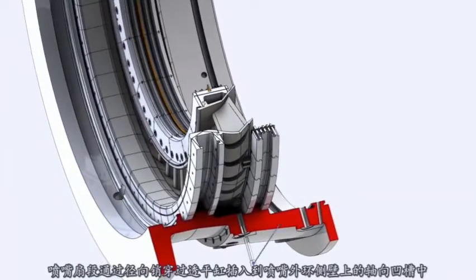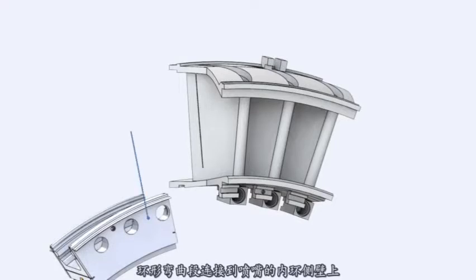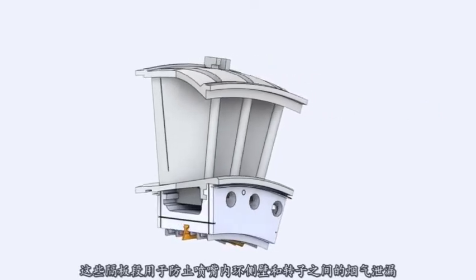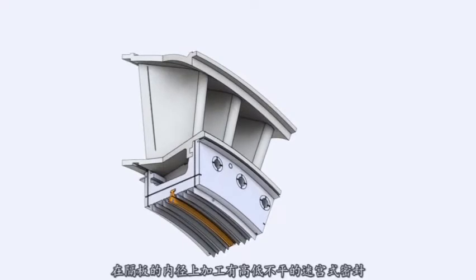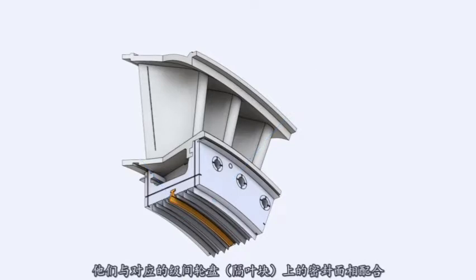Seals are installed between the segments to minimize leakage. The nozzle segments are held on the circumferential position by radial pins from the turbine shell into axial slots on the nozzle outer sidewalls. Annular curved segments are attached to the inner sidewall of the nozzle. These segments are called the diaphragms. Each diaphragm is secured to the nozzle by a pin. These diaphragm segments prevent hot gases leakage past the inner sidewall of the nozzle and the rotor. A high-low labyrinth seal is machined on the diaphragm inside diameter. These seals mate with opposite sealing lands on the turbine rotor spacer.